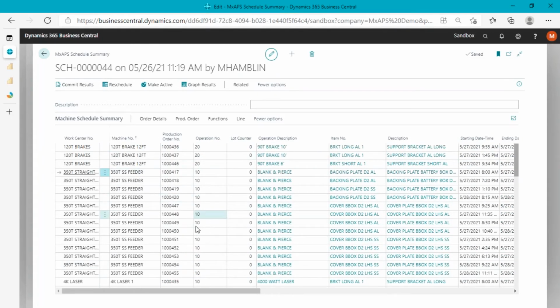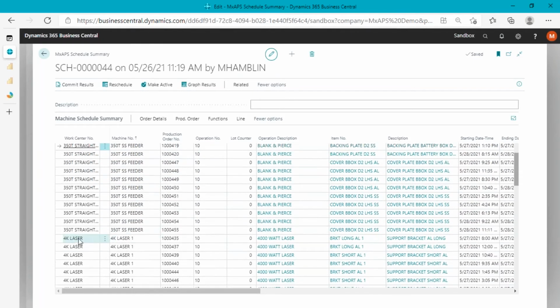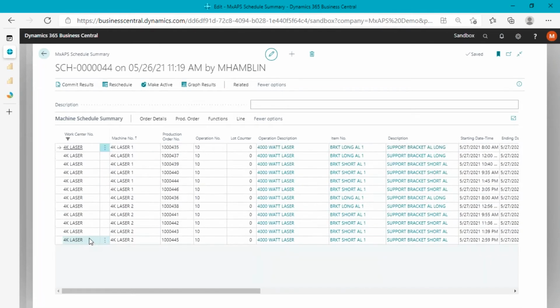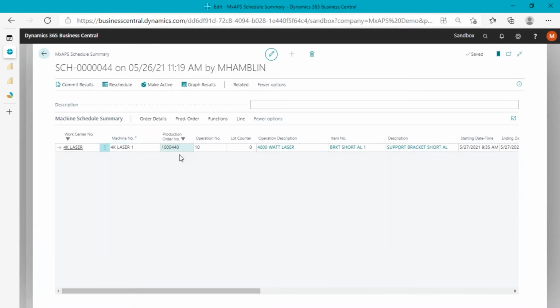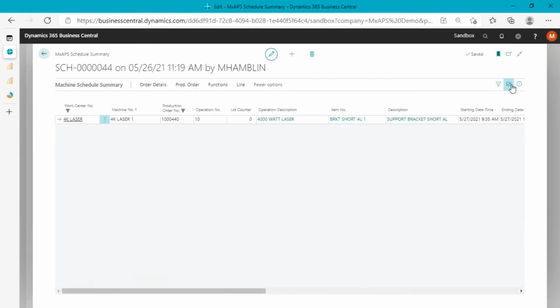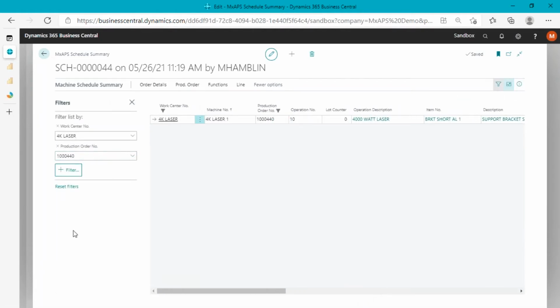And by the way, in here's where I always like talking about hotkeys, but let's say I wanted to come in here and see everything that we're doing on the laser work center. Well, I can just click on that, hit Alt F3, and I can filter on that. If you didn't know, Alt F3 works the same way in the web client as the rotator client. You can hit Alt F3 to go out and filter on individual cells like that. And if you hit Shift Control F12, you get into the focus view, which also gives me that filter pane. So there you go, some hotkeys.